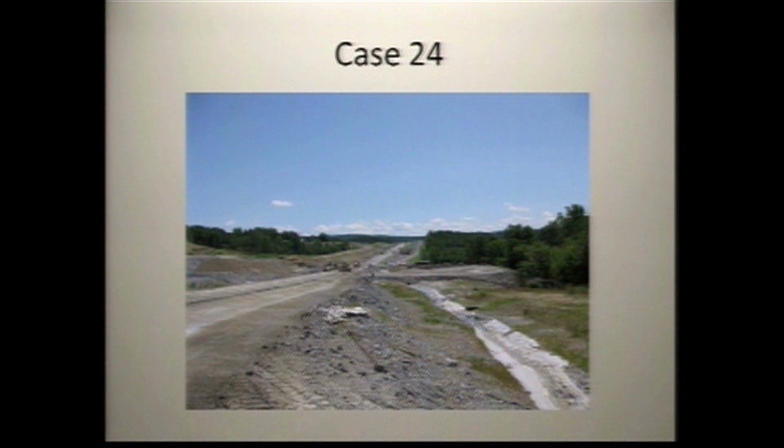And how about here? This was an arterial roadway. Is that an active stream? Yeah, there's actually some dry weather flow coming down there. That's a good eye off to the right. And then that goes off into an active stream over on the right-hand side. Yeah, I mean, just from this picture, that's the best way to put it. There's nothing. I don't see any erosion controls, any sediment controls, any perimeter controls. Again, basics, erosion, sediment.